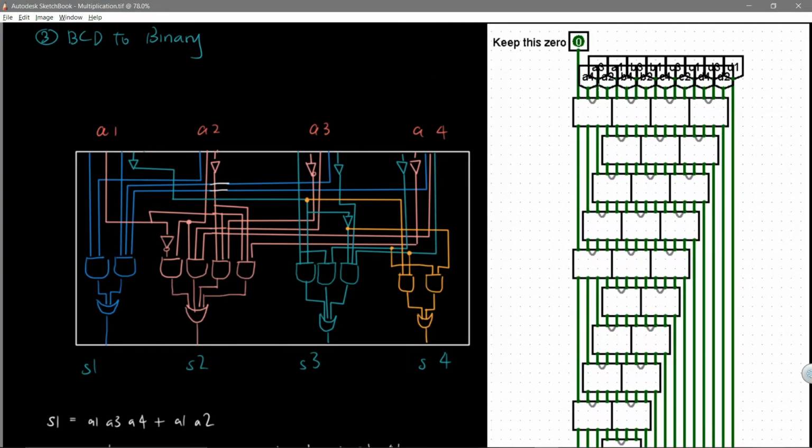And this is how you group them together. The least significant bit of the least value digit, which is the ones digit, is not tested. As you can see, it doesn't go through any of the chips. Due to this nature, and each of these chips having 4 inputs, the last chip at the end will have one of its inputs empty.